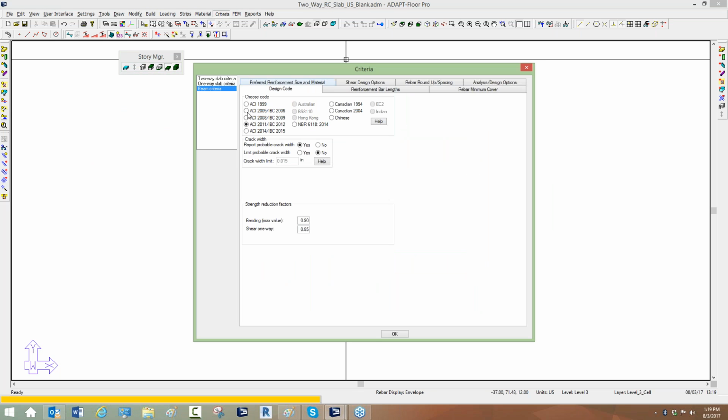If we go to criteria, under the shear, this criteria is set to beam, and these reduction factors are specific to whatever criteria we have set here. So for a 2-way slab, it's 0.85, 1-way slab, 0.85, beam, 0.85. It could have just simply been a programming error, to be honest, where this was never updated. If I toggle to a different load case, those would reflect what the default should be out of that design code.